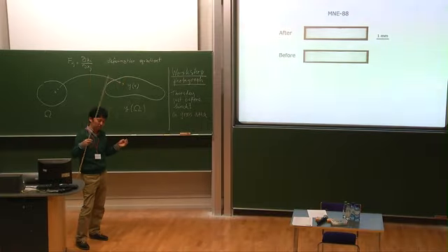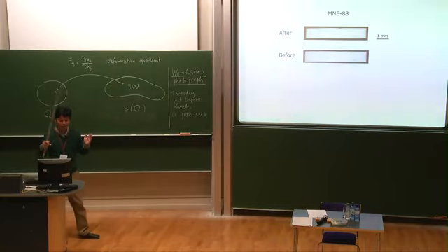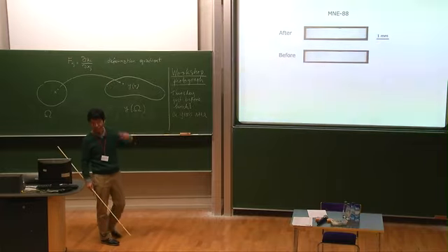So interestingly, if you release the strain after necking deformations, the sample recovers the original shape fully. It is very interesting because in the case of usual necking for a semi-crystalline polymer and glassy polymers, after necking deformations, if you release the strains, they show large residual strains because plastic flow is always accompanied by the necking deformation. But in this case, the sample is an elastomer, so it recovers the original shape completely, even though the sample undergoes the necking deformations.